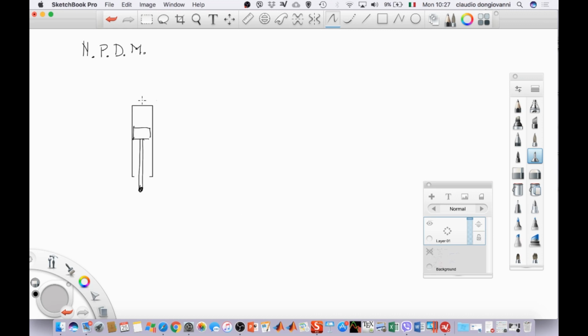The syringe, obviously, as you know, has a connection. You can take the fluid from one environment and send it to the other one. But you want to fill your syringe when the plunger goes down. So this is your suction environment. And in this phase, you want to have only a fluid that goes in this direction, but you don't want to have a fluid coming from the other environment, that is the delivery environment.